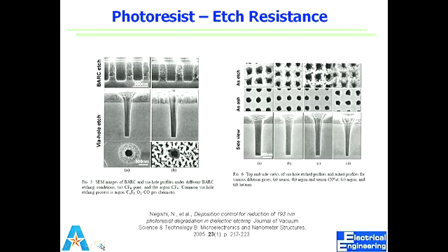In this case as well, we have different recipes used against a photoresist that shows a very different profile of that via. Right? So these are high aspect ratio etches, used for vias. Vias are where we connect different layers of devices with each other. So this is for 193 resist.